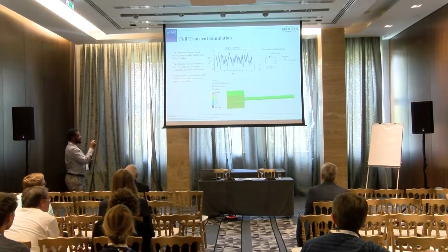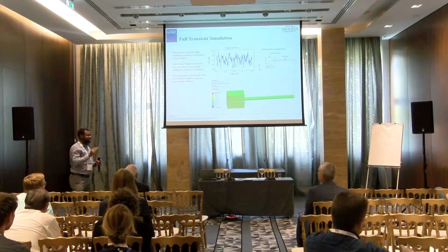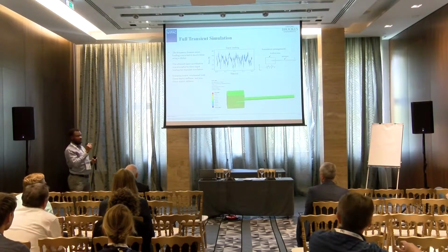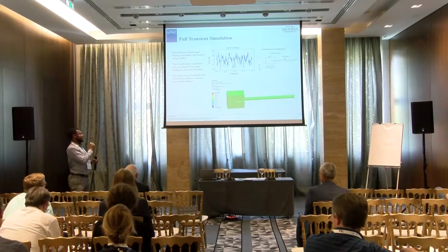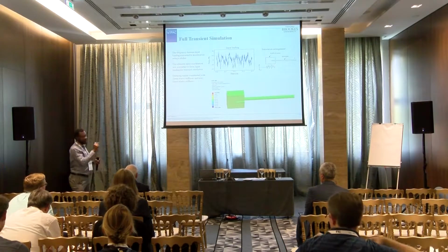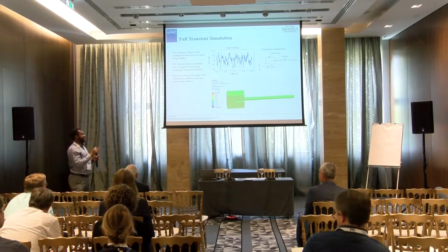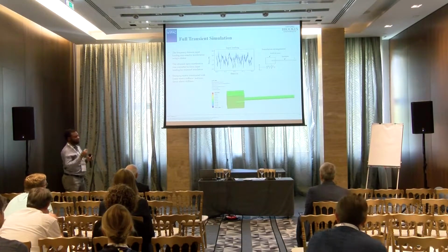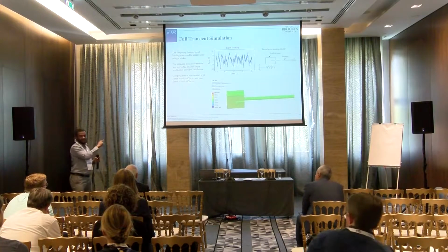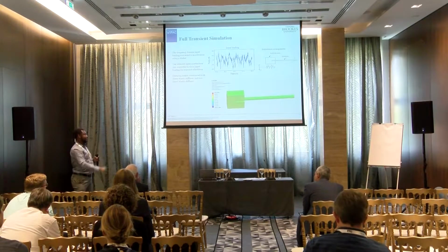This is the input loading, the first loading I showed you, random vibration. We converted the frequency domain data to time domain data. And then the acceleration versus time was also converted to force, because of the mass, the artificial mass, to drive the specimen.